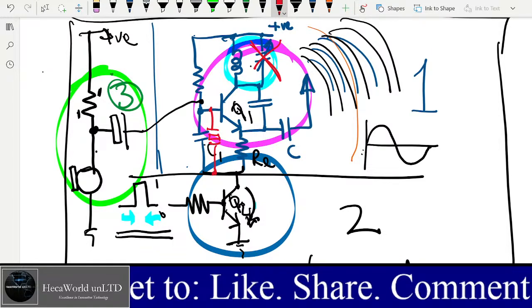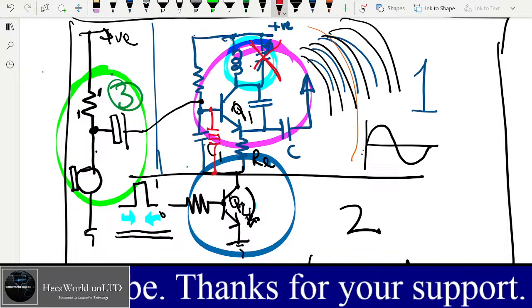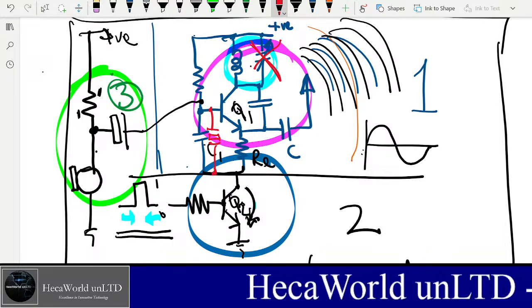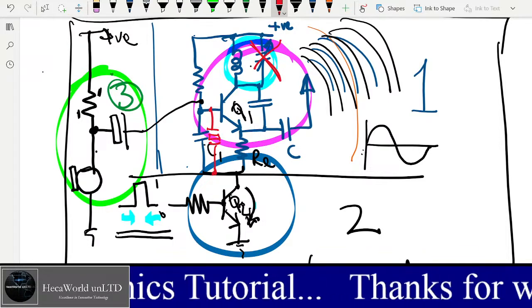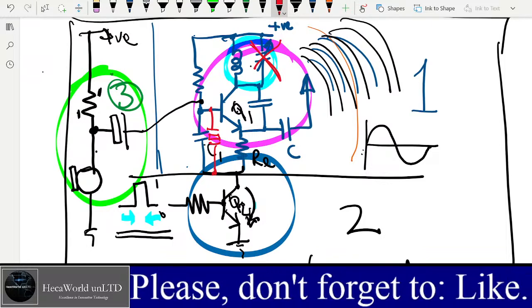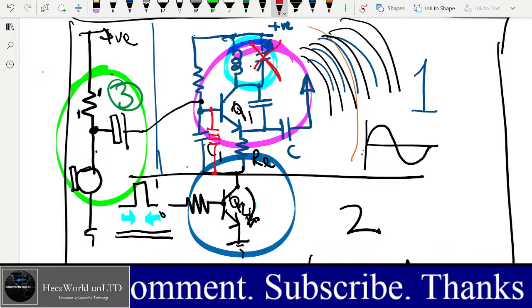Voltage controlled oscillators are not great as remote control devices. And in that case, you must ensure your battery is regulated, and the proximity to the antenna and all the RF circuits is maintained the same or constant at all times. That is difficult to do. So for us, we recommend that you use a crystal for this.